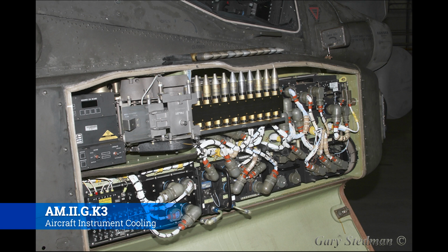Now, fast forward a few years, I'm working at ATS up in Everett, Washington, on a Virgin American plane, and we had a situation with this particular airframe. They were troubleshooting a radio problem, and we noticed that the longer the aircraft ran, the worse the problem got, and new problems would even start to crop up. And then we realized it was because we didn't have a huffer cart hooked up to it to move air around it or anything else like that, we weren't running packs or any number of air sources. The airplane would just get hotter and hotter and hotter, and it would start to cause problems.